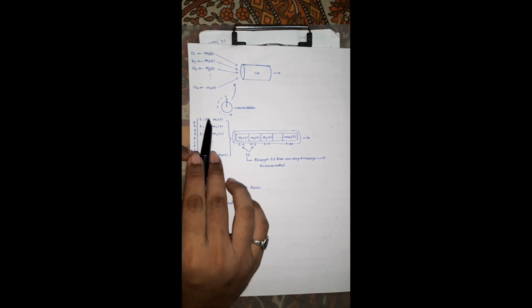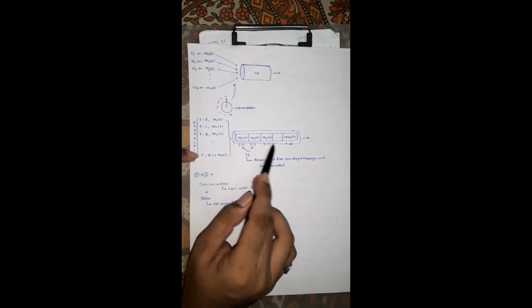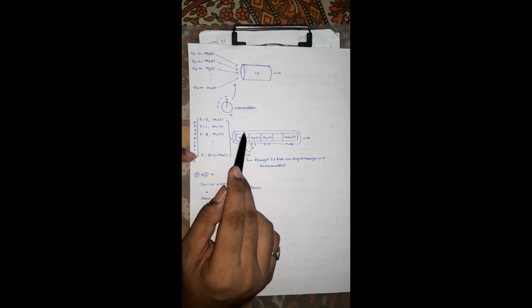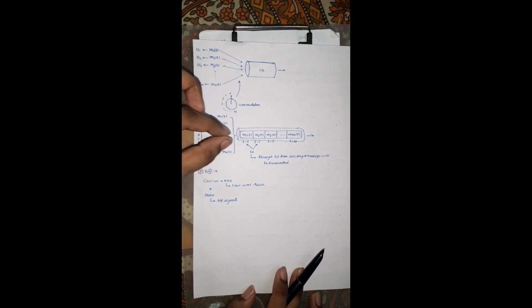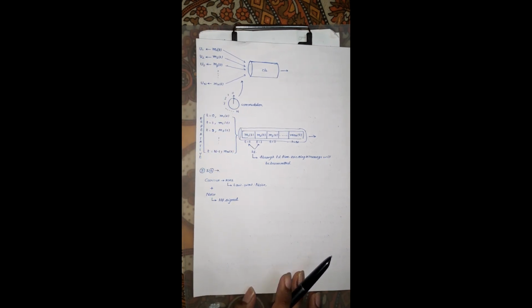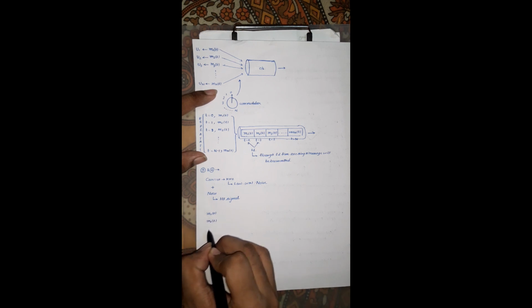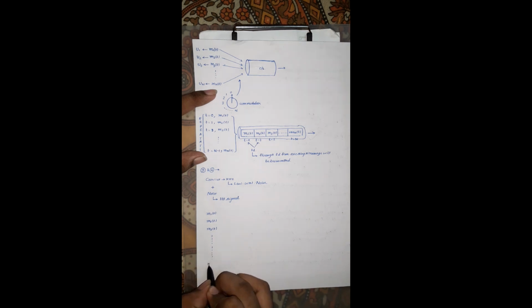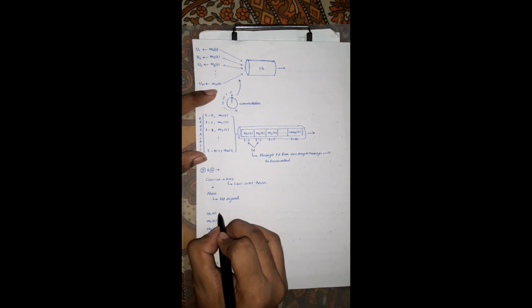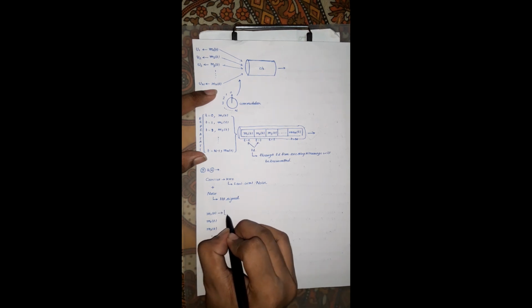Okay, so just to transmit a single message through the channel, we have to put some circuitry just before the transmitter, before merging the messages through the channel. We have to put a circuit, and what is the circuit? There is a filter. Now we will see the block diagram. There is the M1(t) message, one message, second message, third message, and in a similar way, suppose the nth message, and each of the messages will be passed through an LPF, that is the low pass filter.